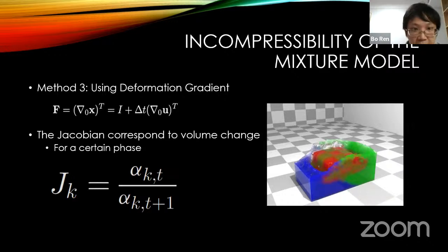we proposed a method using deformation gradients, which do not assume any divergence-free conditions. We think that the deformation gradient can be used in fluid simulations, and the Jacobian of the deformation gradient can be calculated from the volume fraction change of one particle.